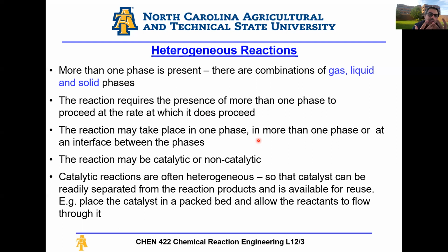Previously, when we were talking about ideal reactors, for a CSTR, you sort of assume that everything is in the liquid phase. For a PFR, you also assume that everything is in the liquid phase, within the context of our course. And we've touched a bit on having a gas phase reaction, where you now need to account for volumetric changes with the number of moles.